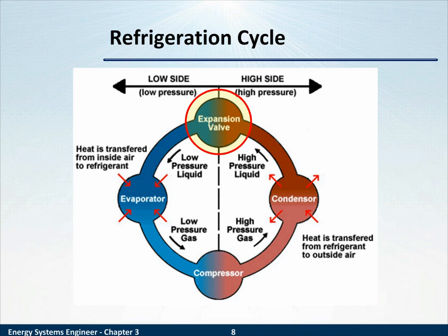The next component is an expansion valve. The expansion valve converts a high pressure liquid into a low pressure liquid, and that expansion makes this low pressure liquid cold.